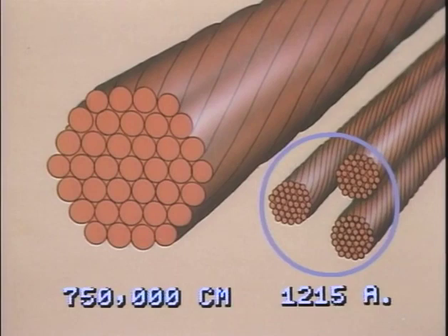The higher ampere rating is due to the fact that resistors in parallel offer less resistance than resistors in series. Increased current rating is one of the advantages of conductor bundling. Also, because bundling counteracts the increased resistance caused by skin effect, the amount of power loss in transmission lines is also reduced by using bundles.